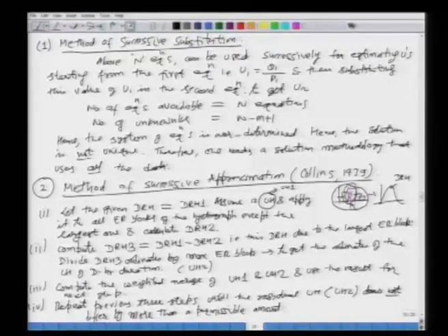So, what we are saying basically is that we keep on iterating. We assume a certain unit hydrograph, we calculate the DRH due to the largest ER block, divide by the largest ER to get the revised estimate of UH, do some weighted average, do the whole process again and keep on doing it until some level of acceptable error is reached in terms of the unit hydrograph ordinates or the total volume or whatever criteria. That way we can find the final unit hydrograph which uses all the data. So, this method is much more accurate than the first one.